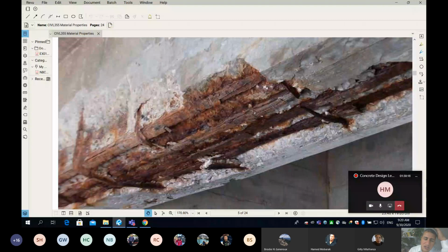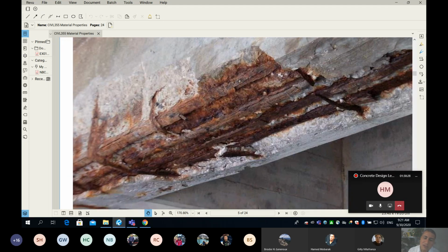This is lost naturally, because when rebar corrodes, it expands and pushes out the outside layer of concrete. And you can see the cross section. Not sure how clear you can see, but the cross section is lost. If I start with 20 mm and after a few years of corrosion maybe right now I'm at 10 mm, only 10 mm. And I myself have been to some projects where there is no rebar at all. The rebar is completely gone, completely gone.